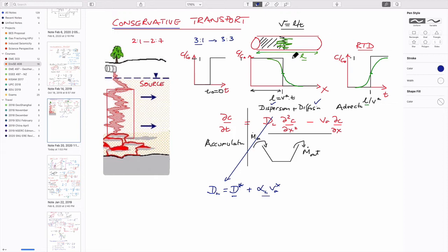We know that when this dispersion coefficient is equal to 0, then we expect this sharp front to occur. And we know that when this dispersion coefficient is greater than 0, then it will not be this boxcar distribution anymore. And we also know that as it gets larger and larger, then it'll get flatter and flatter. So that's kind of the behavior, because it gets more diffuse.